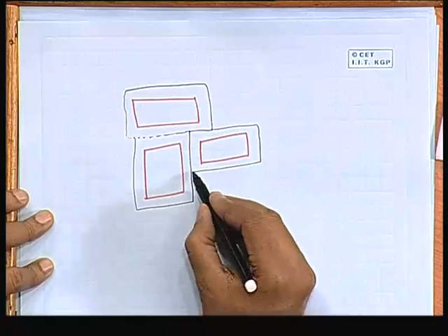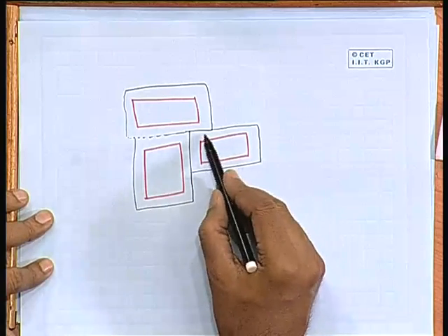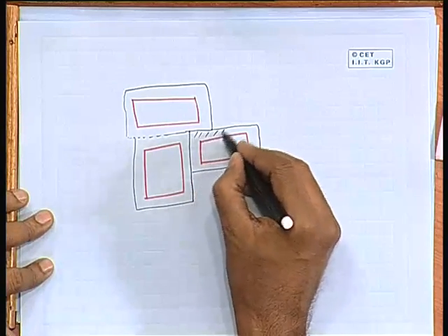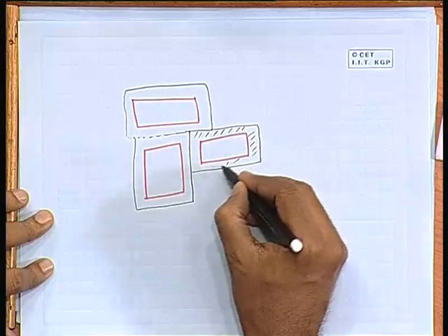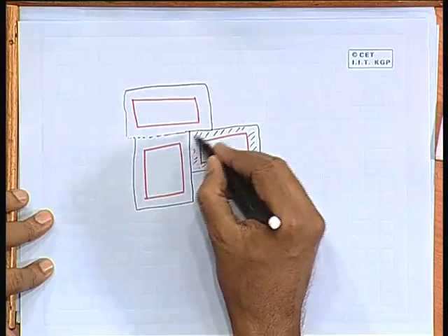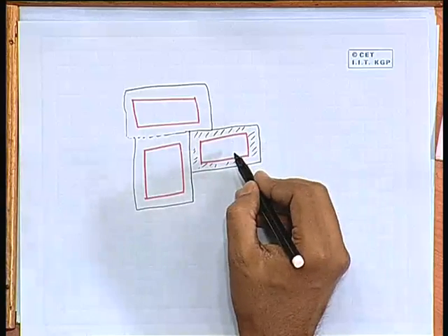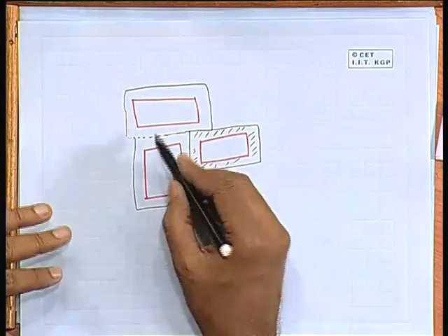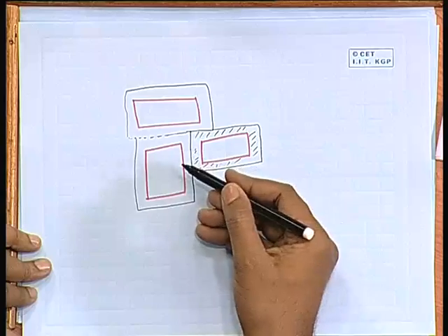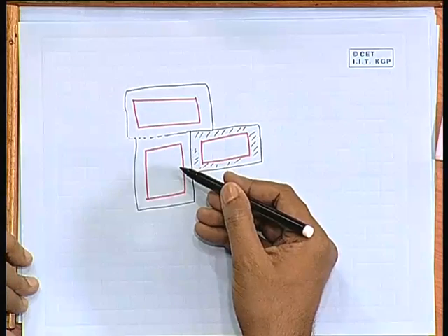The reason is that the additional area you are keeping aside in the boundary of these modules is actually the space you are keeping for routing. So, once you do this, then the placement and the floor planning problem becomes very similar. So, there are some tools where floor planning and placement are done together, and some technique like this is also adopted. Okay, fine.